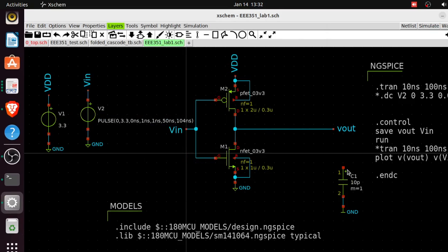So what does this mean? It means if this is the load you want the inverter to drive, the load would affect the inverter's performance big time. So maybe what this capacitor is doing is shorting, because with changing voltages with frequency, a capacitor becomes a wire.